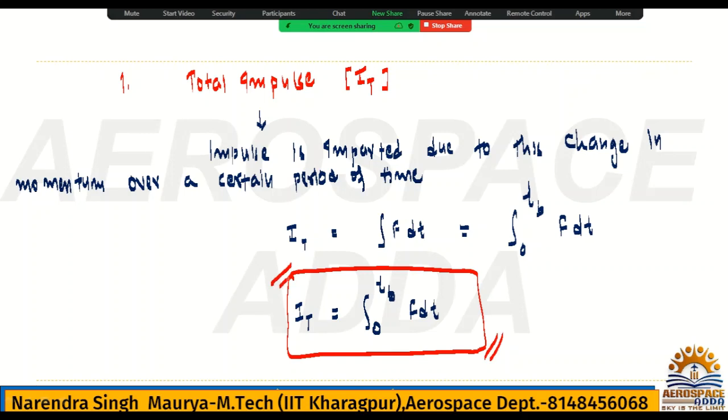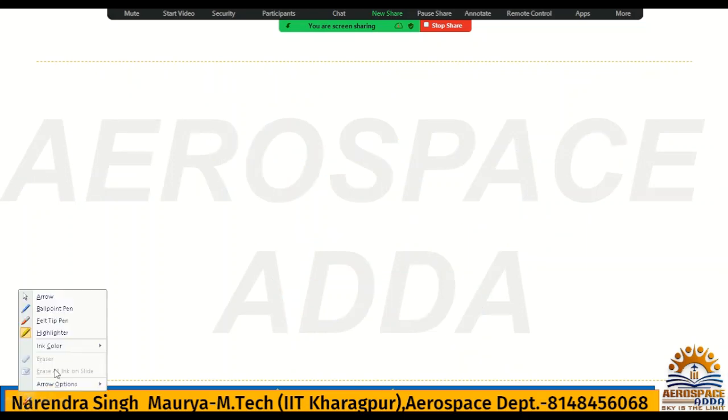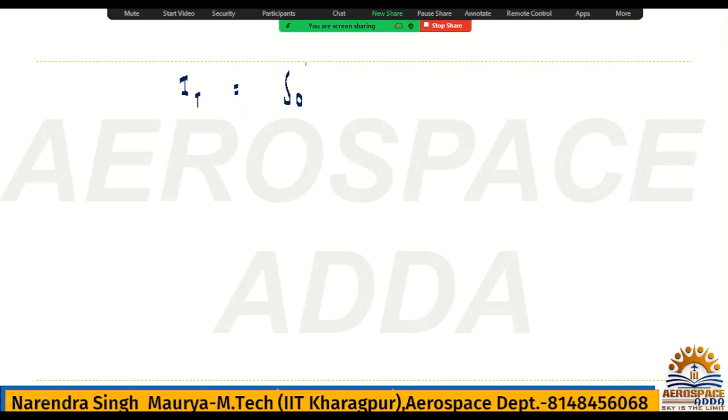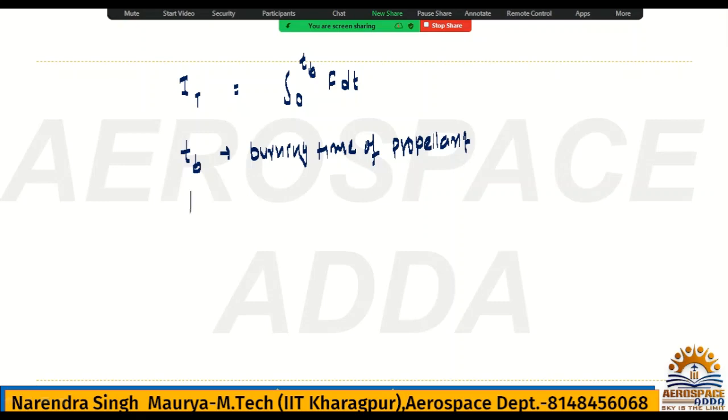Okay. Now here, whatever the formula you have for the total impulse, I T is the integral from 0 to TB of F into dt. What is the TB? It's the burning time of the propellant. Okay. And obviously it is burning, so thrust will be produced.